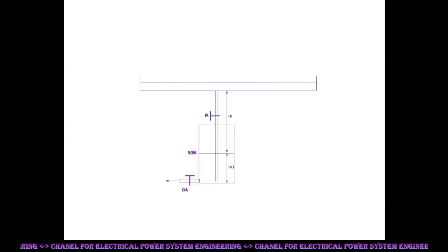More details are available in the video Active Power Matching Mechanism. The power system is also operating the same way. Generator is injecting active power into the system. Users' load is drawing active power from the system. The frequency is steady as long as power injection and draw are equal.